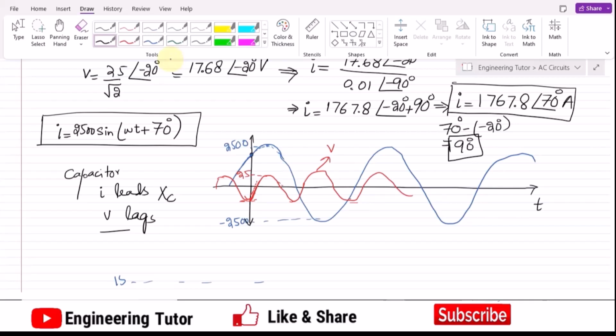But what is the difference between the inductive reactances and the capacitive reactances when voltage and current flows? In inductive circuits, voltage leads by 90 degrees from the current, while in the capacitive circuits or in the capacitive reactances, the current leads the voltage 90 degrees, okay.